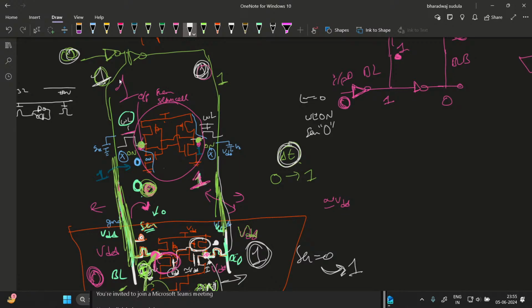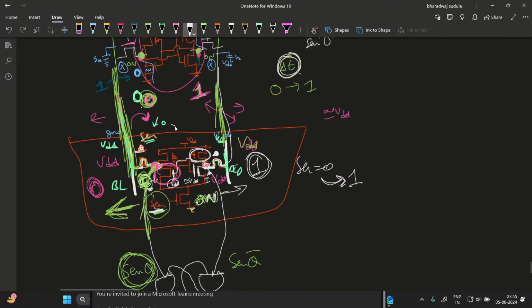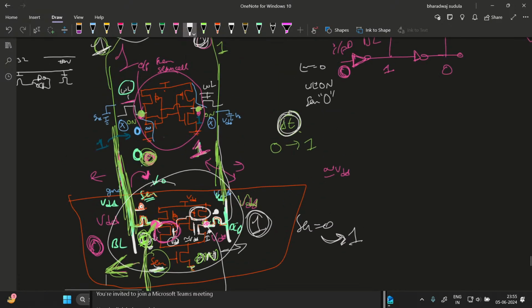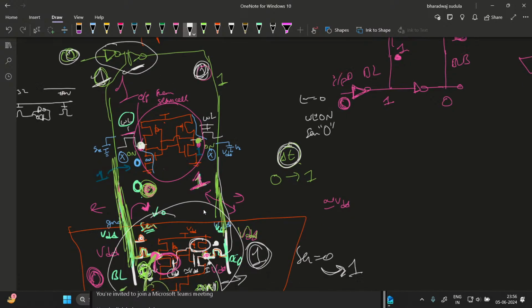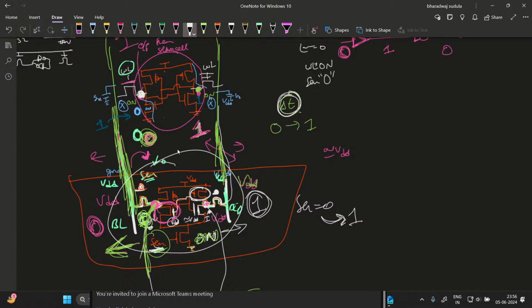So what I'm trying to say is, while designing the write circuit and this SenseAmp, check where you want to store the data in the SRAM cell. If you fix the left node as your information bit, then design the write circuit accordingly. Otherwise your information will be inverted, because the SenseAmp and write circuit won't agree with each other.